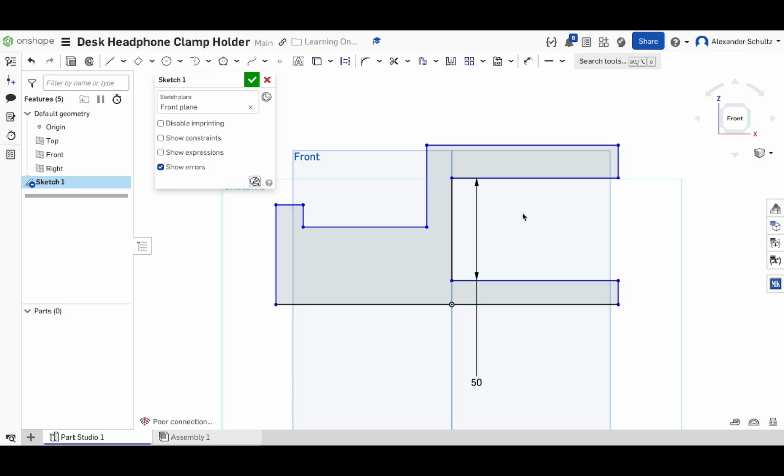All right, so now we've dimensioned that, we can dimension these parts, which are the thickness of the clamp. These parts have to be pretty thick because I've actually made a version of this myself, and if you clamp it down, the edges might tend to bend, so you want to make it thick.